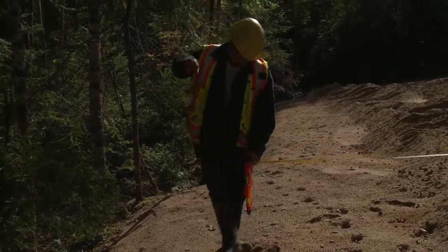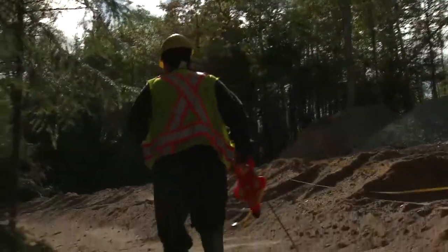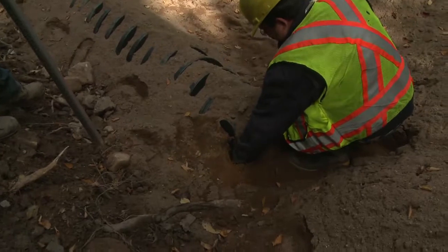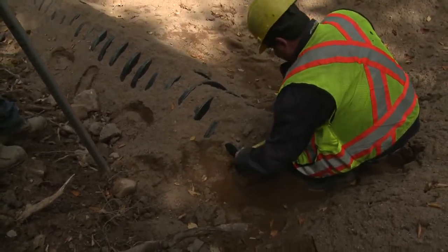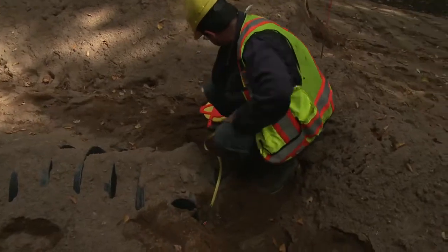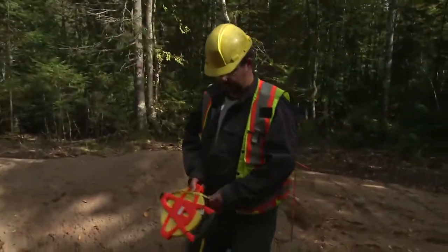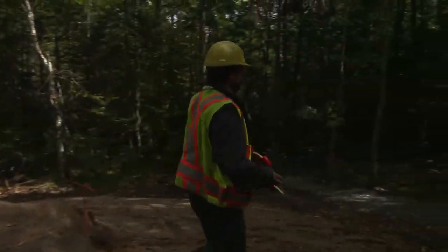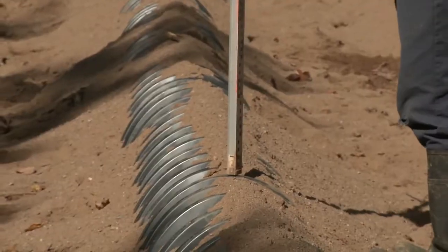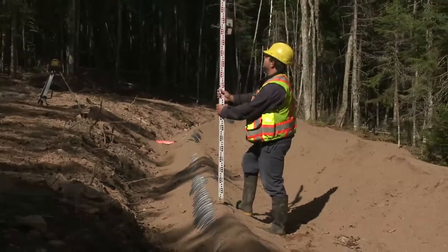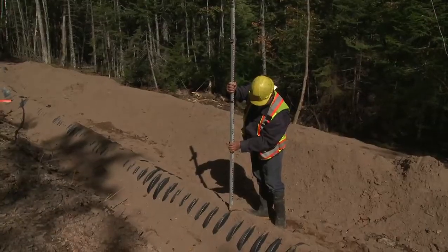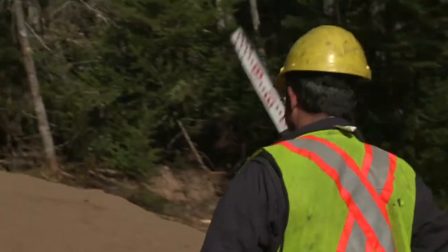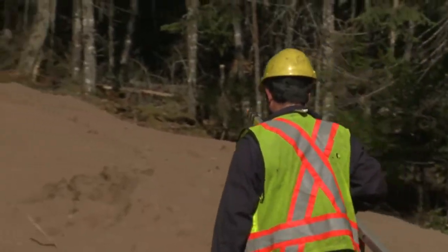The depth of the filter sand in the trench and the depth of the sand in the downslope buffer at 5 meters from the trench are verified at several points. The length and the width of the trench are verified. The chambers are checked for level. The number of chambers, end caps, and splash plates are recorded.